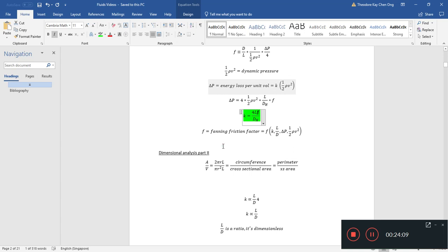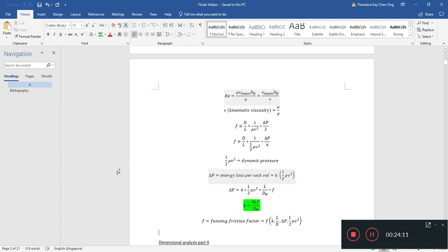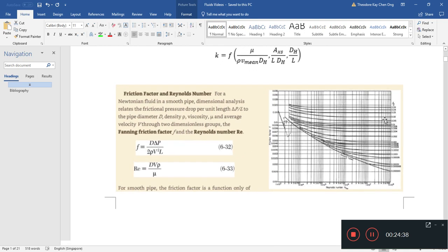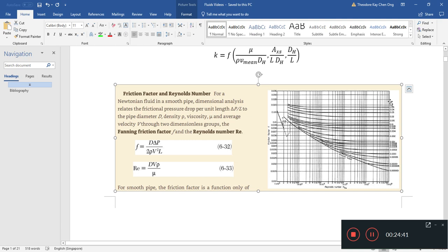And how are we going to find the Fanning friction factor? We're going to look at the Reynolds number, and we're going to look at the fluid density, fluid viscosity, fluid speed, and of course hydraulic mean diameter again. So this is a very important quantity to know. And we'll go look at this graph. It's either in the laminar regime or the turbulent regime, or somewhere slightly in between. If it's in the turbulent regime, we will need to know what these numbers are. Now I have not covered what these numbers are. They have something to do with the surface roughness of the tube.